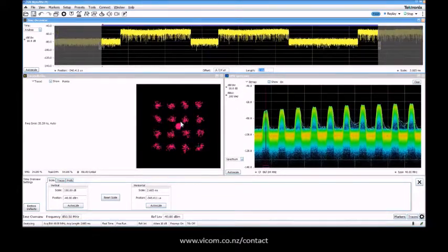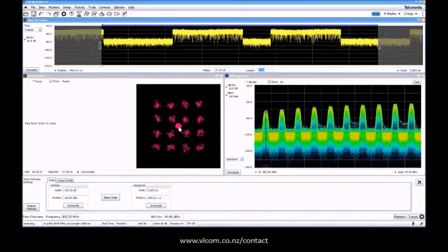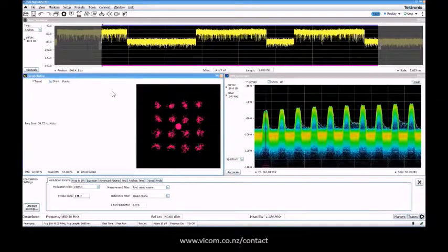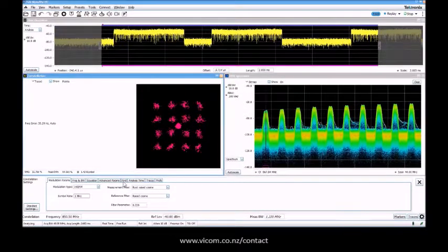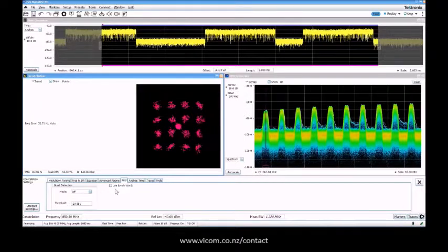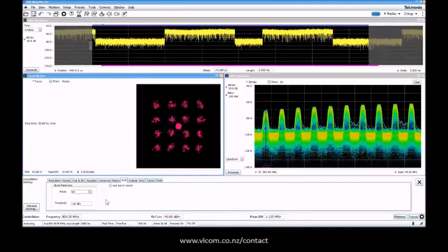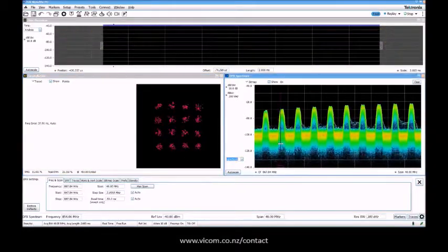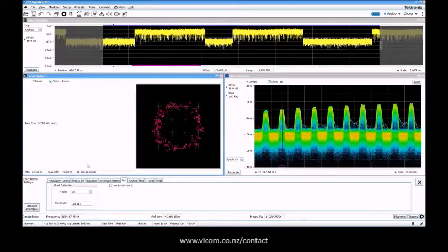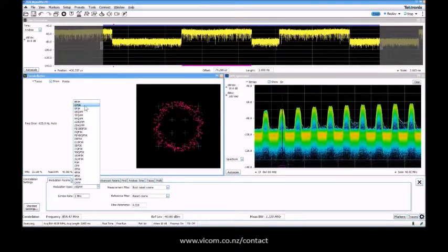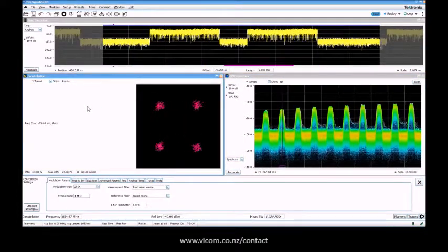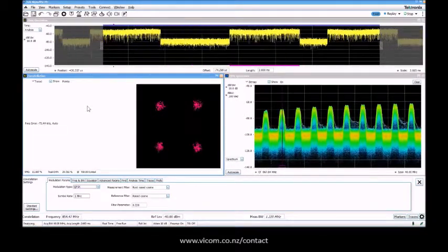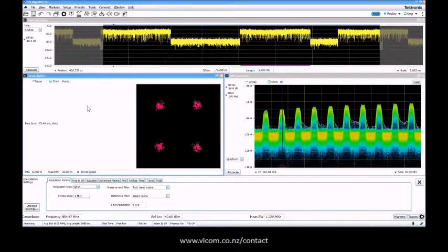And now here you can see that I have points in the middle here, and these points refer to nothing. So I need to make sure that the software knows where it's not working. So there's a find here, and here you can use burst detection. So if I put it on, it will only look at the burst and demodulate. So now I can move over here again. Of course there's a different modulation. That was QPSK, and this was the IQ imbalance from time to time. So let's see if we can capture one of those from time to time.